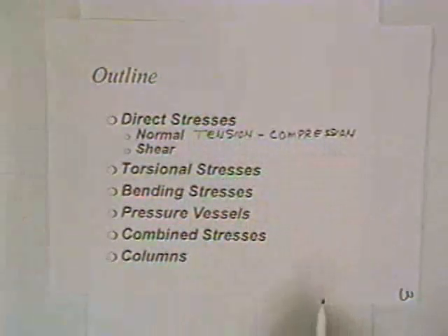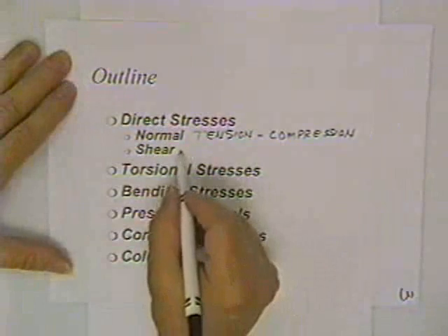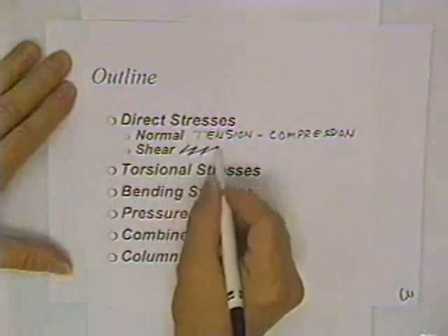Tension stresses would be, for example, in a piece of wire when you pull on it. Compressive stresses would be the type of stresses that would be in something when you press on it. And shear stresses are slightly different. Shear stresses are wiping stresses. Those are shear stresses right there, when you rub your pencil across a page and little pieces of it come off on the page.